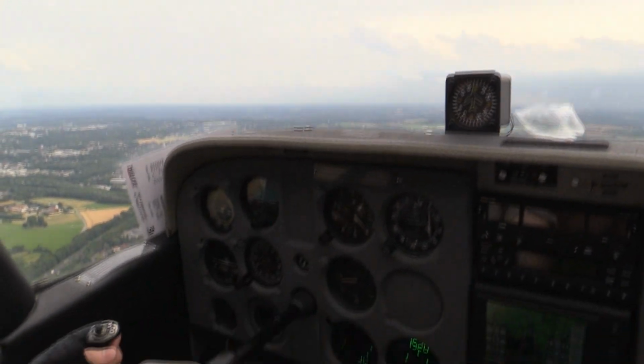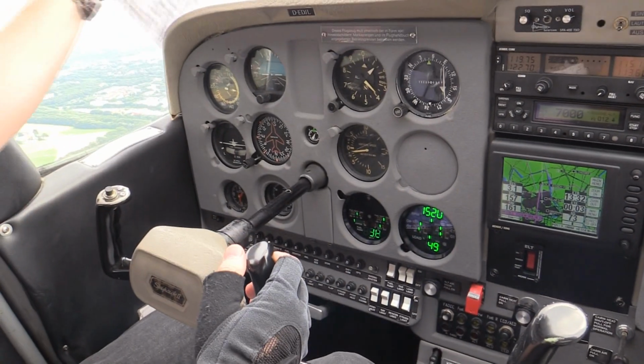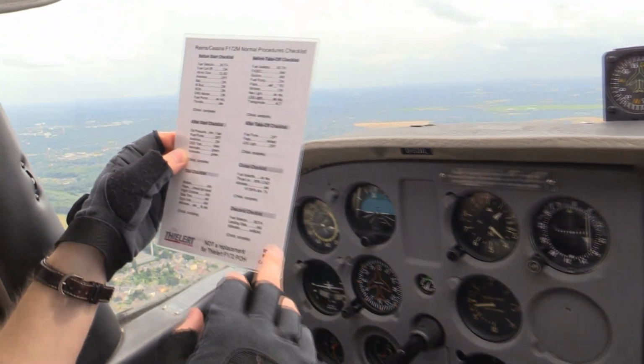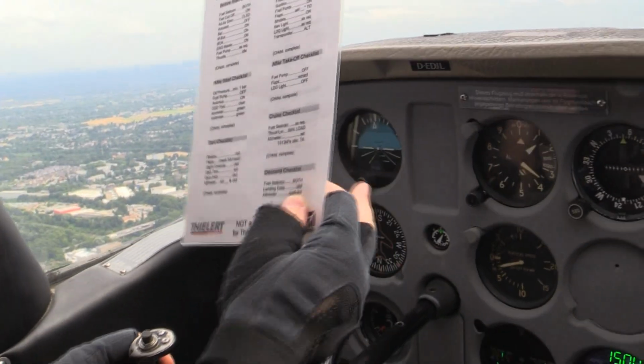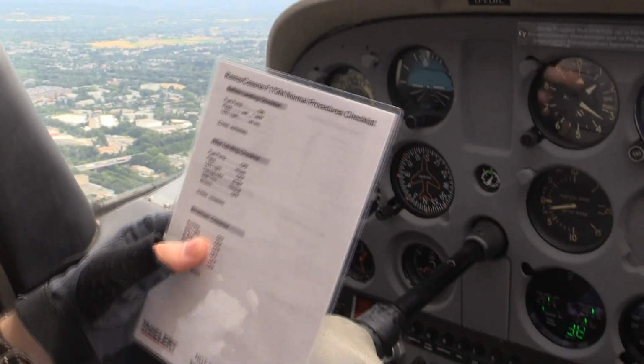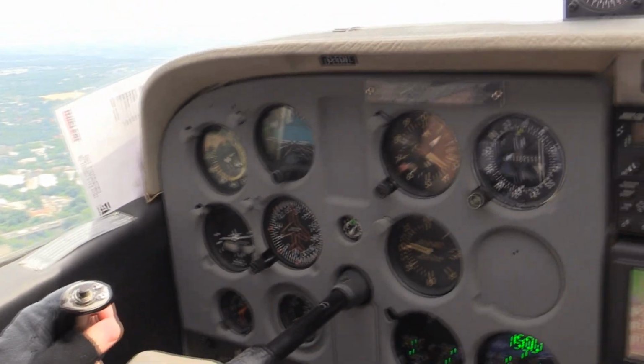At this point, I'll already turn on the fuel pump again. And let's just go for the descent checklist. The fuel selector is on both, landing data is checked, and the altimeter is set to 1017 now. And that concludes that checklist.